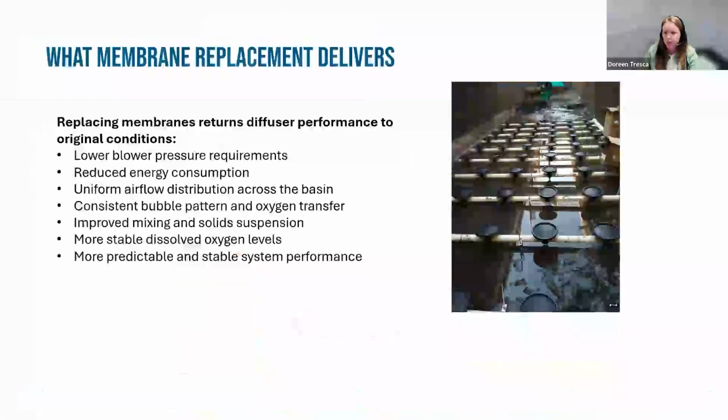When membranes reach the point where cleaning is no longer effective, replacement is how you can bring the performance back to its original condition without installing a totally new system. With new membranes, airflow resistance is reduced, which is going to lower the blower pressure and the energy demand. So you're going to go back to that like-new efficiency from when you first installed the system.